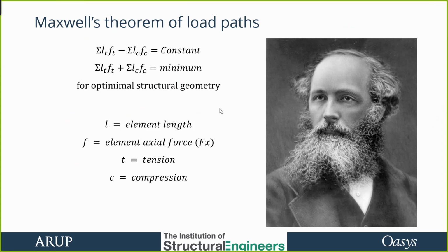Now, optimizing shapes of trusses, for example, we could use Maxwell's theorem of load paths. James Clerk Maxwell, who you may have come across. When he was not creating structural analysis theories, he was also busy inventing electromagnetism, color photography, thermodynamics, and so on. Yeah, he was a busy chap. So his theorem is if we sum up the length of all the elements multiplied by the forces, either tension or compression on them, and depending on the signs we use, are we using tension and compression with the same sign or opposite signs, depending on whether we use a plus or minus here.